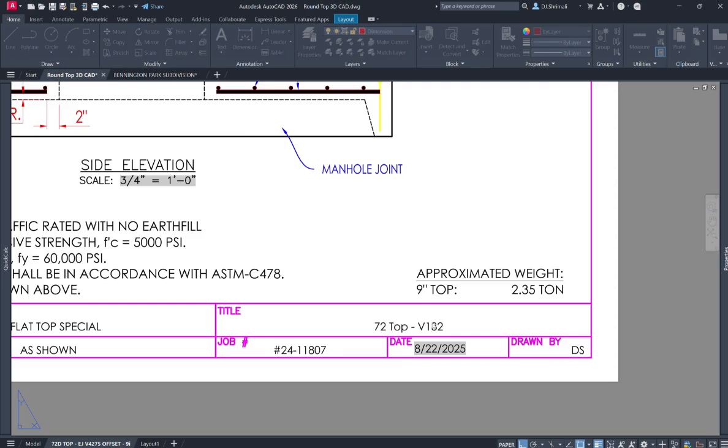Okay, so you will use the mask command, copy the volume. Okay, so whatever the number that you get in front of the volume, copy that, paste it into the calculator, and then divide that number by 12 by 12 by 12 3 times.